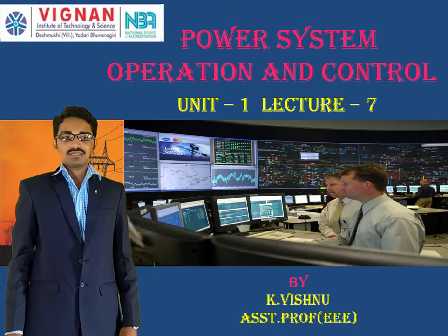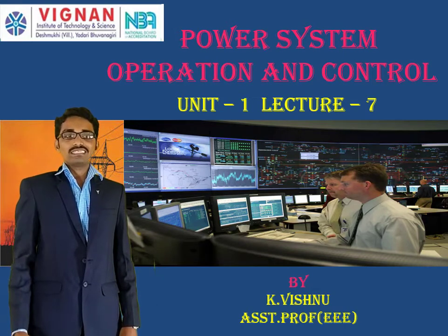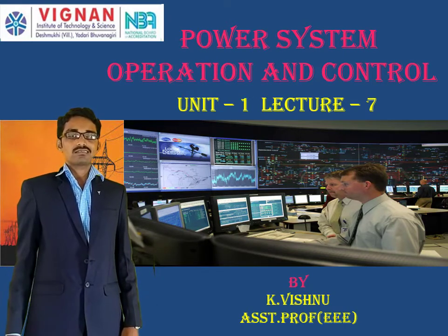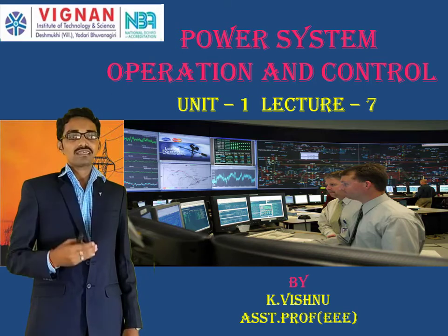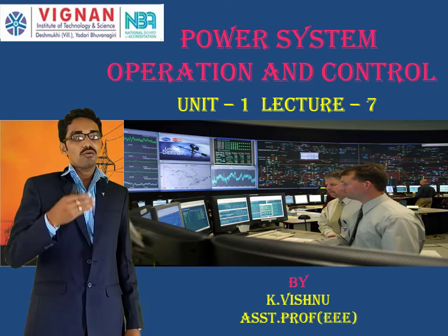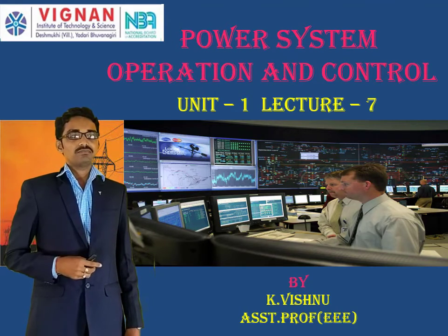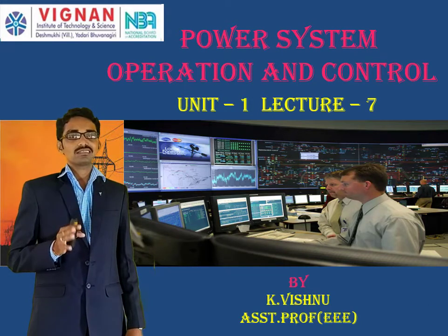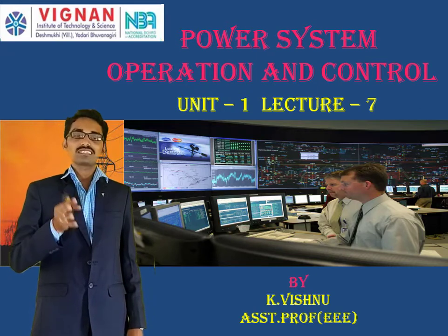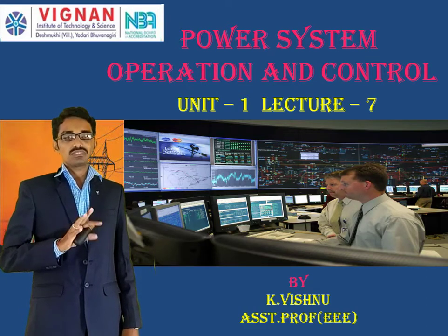In the last class we have seen the uncontrolled and controlled cases of operation of steady state analysis, and then we have seen proportional plus integral control of single area system. In that we have seen our static frequency change, that is delta F static, is made 0. And then we have seen the load sharing between the two generators, how the load sharing happens, and we have got some equations of load sharing between the two generators.